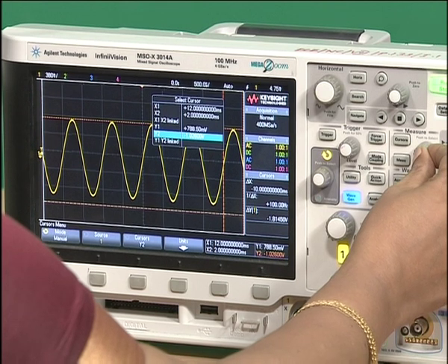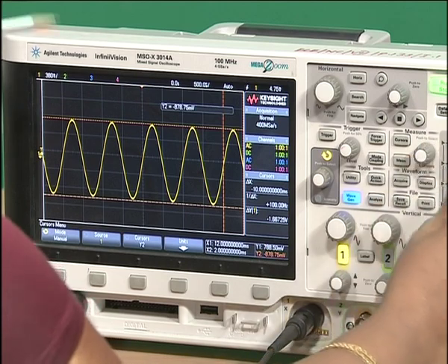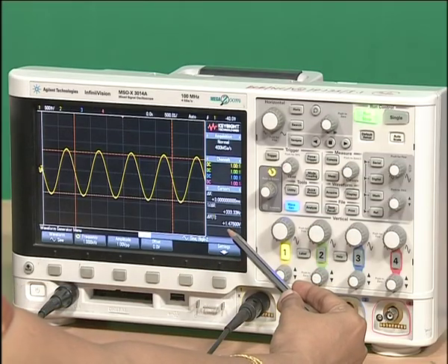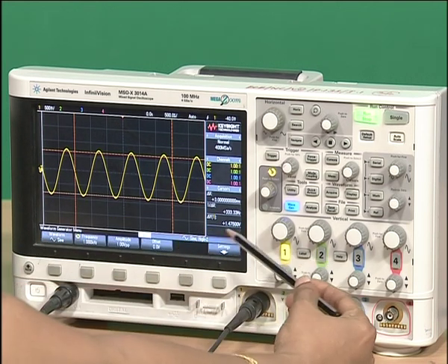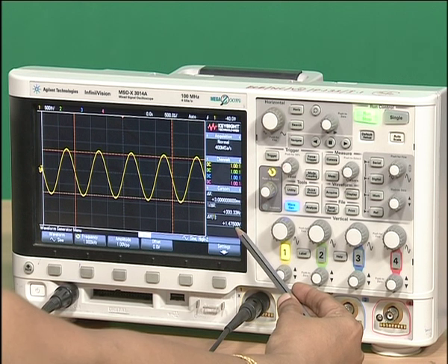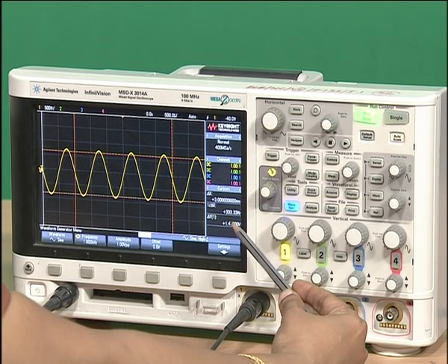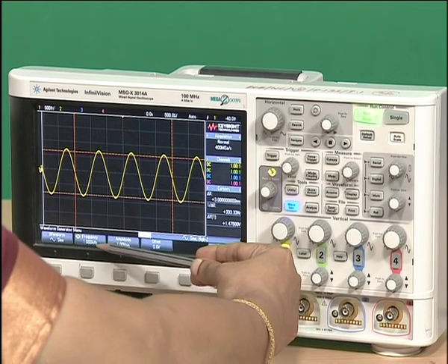So, let us verify the peak to peak amplitude. We will adjust the y cursor now. And the peak to peak amplitude that is read is about 1.475 volts. Now, at the cutoff frequency what you can observe here is about 1.475 volts. The expected one is 1.414. This is because of the tolerance that we have in the capacitance. What we have used is 10 nanofarad, so with the expected tolerance this can deviate. So, it is closer to 1.414 and the cutoff frequency that you can see is 1 kilohertz.